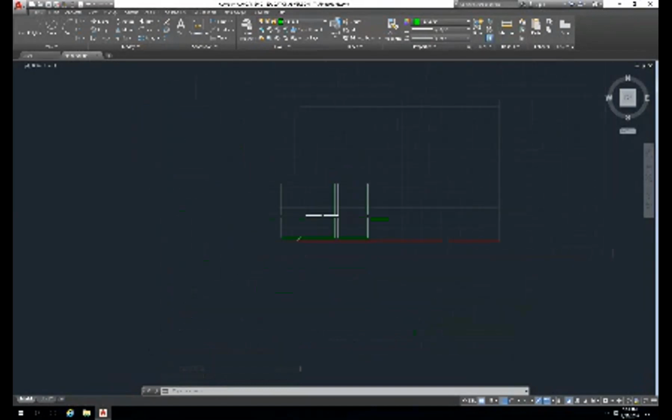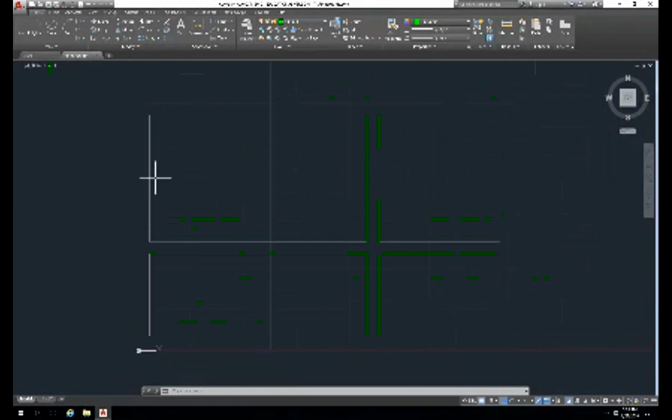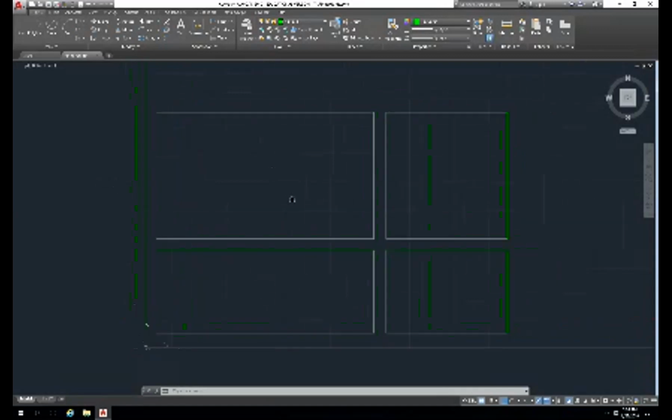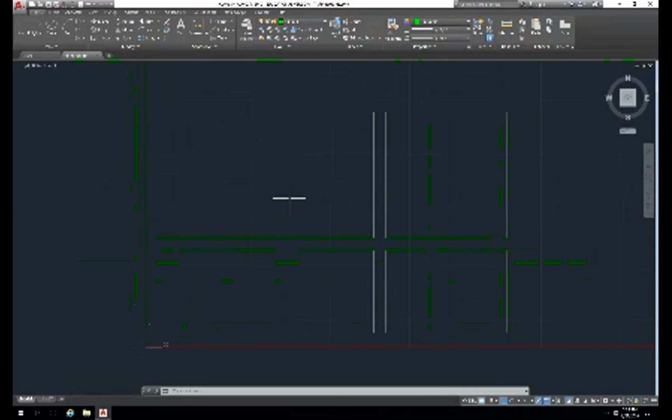See, AutoCAD needs 3 buttons. That's why even the laptops that are used for drafting are usually special laptops in the quote unquote workstation class, and they have 3 buttons on the touchpad. I'm using a consumer class laptop, but I'm not running AutoCAD on it. It wouldn't be able to. I am remoting into a machine where I can do this. But I am using a wireless mouse so that I have 3 buttons, so that if I click the middle button and keep it down, I can drag. And the wheel on the mouse allows me to zoom in, zoom out. That wouldn't be very easy on a laptop with the touchpad either.